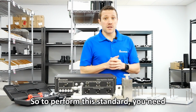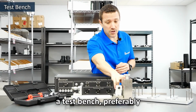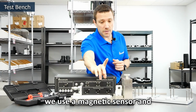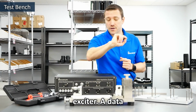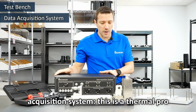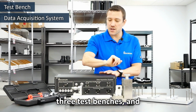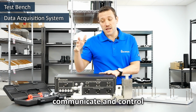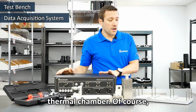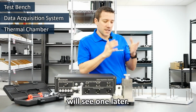So to perform this standard, you need several items. First, of course, you need a test bench, preferably a temperature-resistant test bench. Here we use a magnetic sensor and exciter. A data acquisition system. This is a Thermal Pro acquisition system that can handle up to 3 test benches and communicate with and control a thermal chamber. Of course, you might also need a thermal chamber. We will see one later.